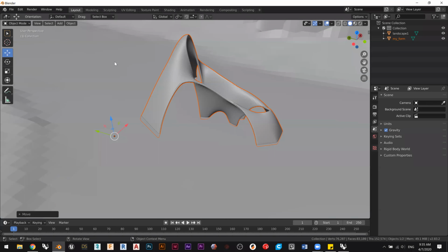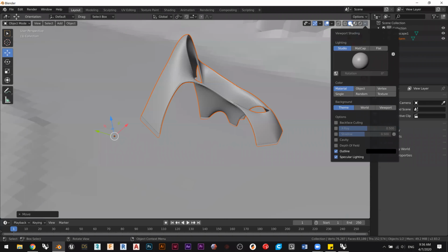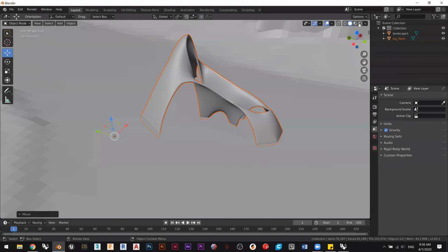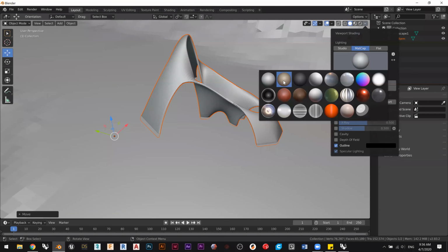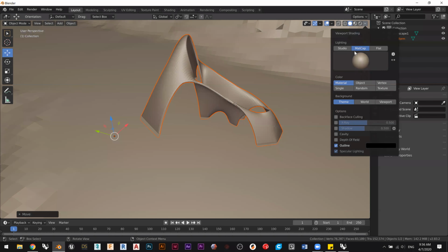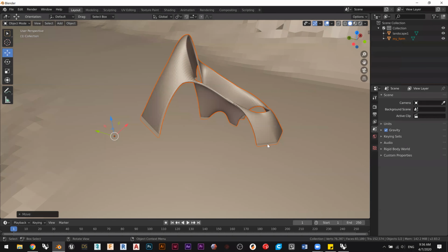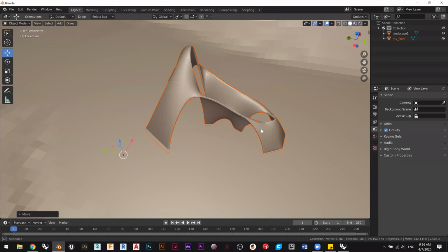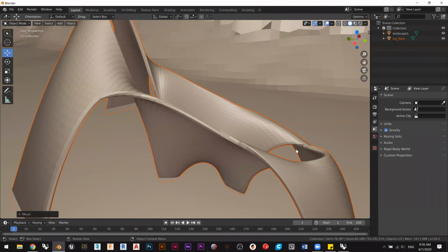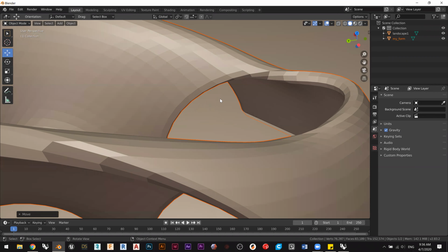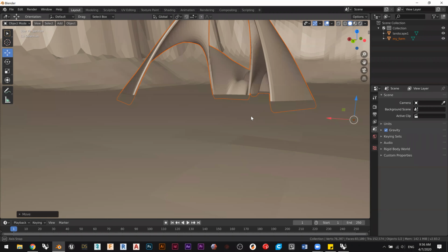If the landscape is black, then you go to the material settings, viewport display settings, sorry. Change to matte cap. Change the matte cap to whatever color. And instead of material, use object color. That will fix the shading. So we have this thing working. Seems to be nice. Okay.